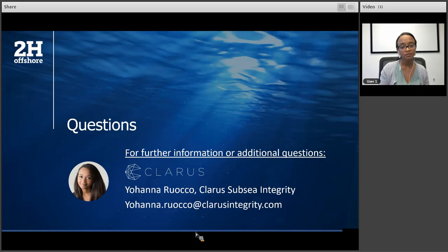Okay, thank you. Next one, should I consider NDE of retrieved components? Absolutely. I think there's a lot of value in getting data on components that have been retrieved. Typically, for some subsea components, we just do visual inspection, but for rigid jumpers especially, we have done NDE, and that has helped us identify what the corrosion hotspots are for a particular jumper configuration and field conditions.